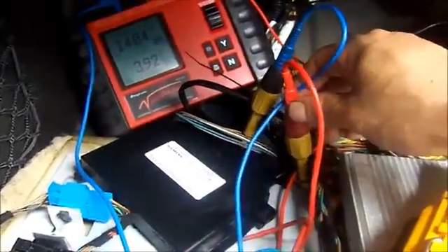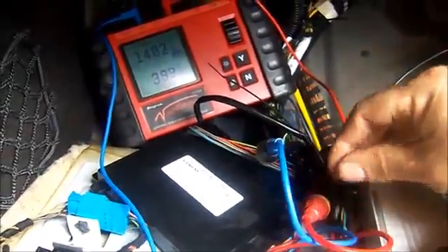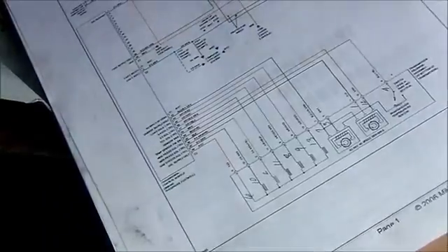Okay, here what I'm looking at, I got my channel 1 on the red and light green wire that comes from the relay box, fuse number 1, and that feeds on to the transmission control module. And then I got my lead channel 2 on pin number 38, the red wire. That's my feed voltage for my solenoids, and I have to have battery voltage going out to there on pin number 6.